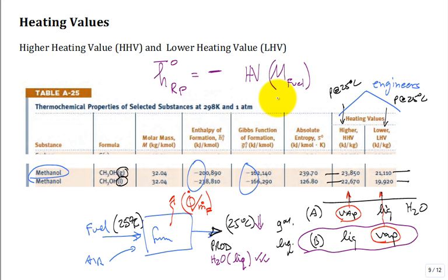Now you say to yourself, for the enthalpy of combustion, either I pick the lower heating value or the higher heating value. It did matter for both of those. So you just have to decide which value. Probably the higher heating value. If you do that, then the water in the products goes out as liquid.